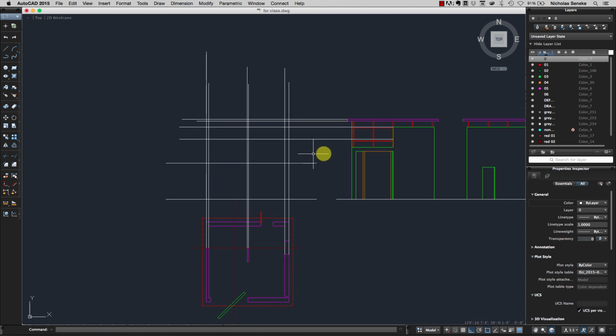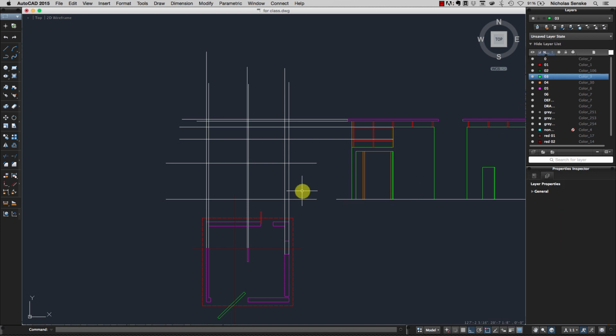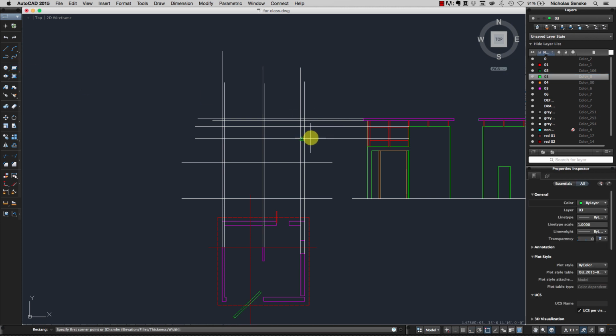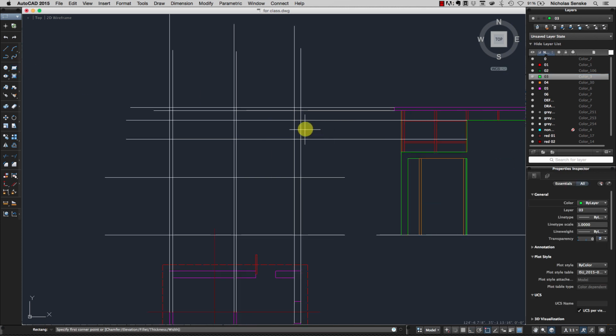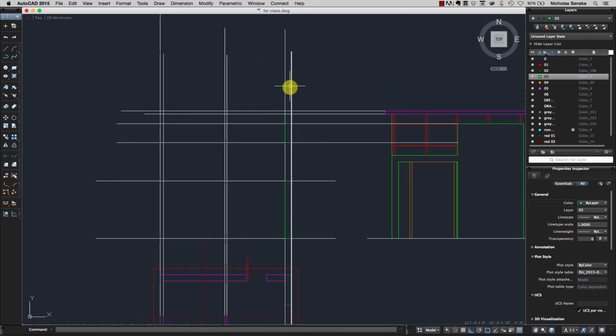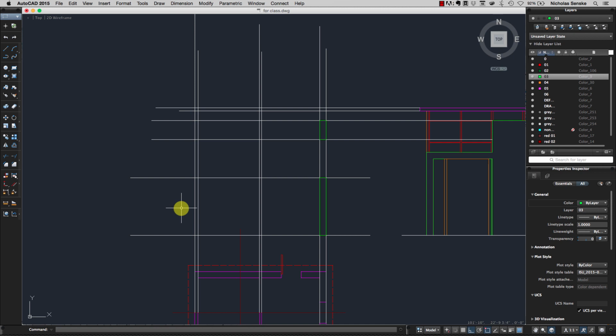Okay. Now something you can do with this, while you're working with it, is you can just use another color, and you can use these lines, and then you can use the other color on top of them to actually show the pieces that you want to keep. So it's a good way of doing this without actually deleting the construction lines that you drew. You can use the construction line tool, but I find it kind of cumbersome. The construction lines, we use these in the elevation demo. I don't know. This is maybe a little bit messier, but it's easier for me to control.